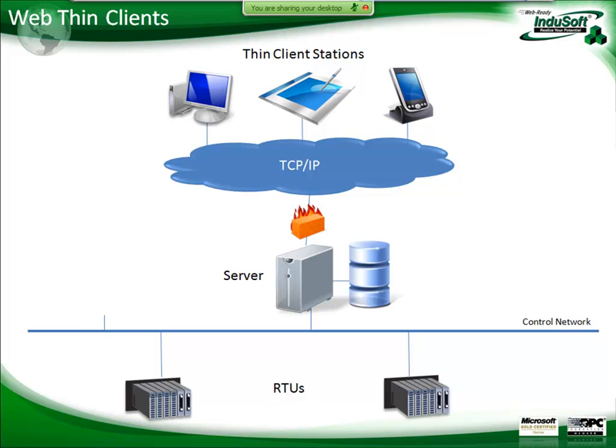So the InduSoft Web Studio running on this computer, talking to the PLCs, collecting data, saving this data to the database, works as a shield for this control network, as well as a bridge, a gateway between the remote users, the thin client users, and the information from the process. So the thin client users do not hit the control network directly.